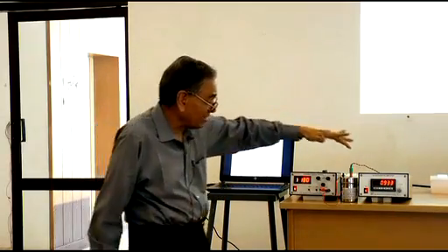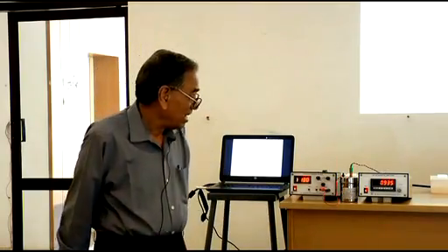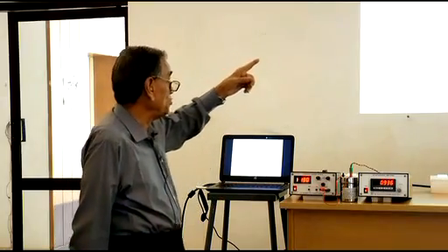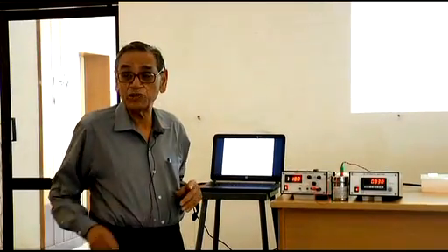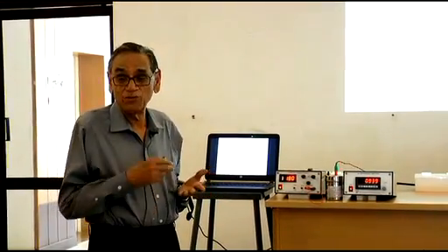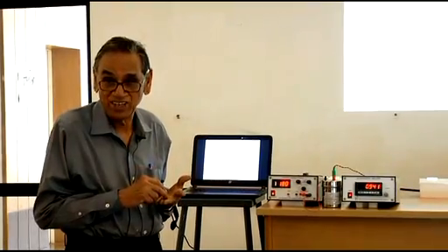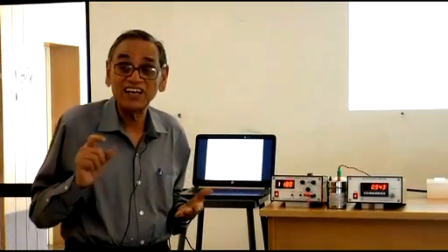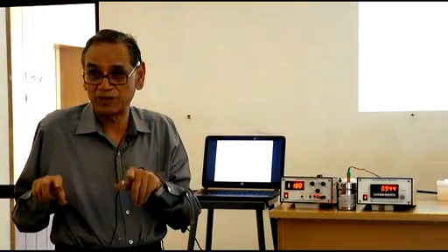The third column gives the differential amplifier reading in millivolts. It is 1.78 millivolts. Convert it into microvolts by multiplying by 1000, that is 1780 microvolts. The couple has a thermo power of 40 microvolts for 1 degree difference in temperature.